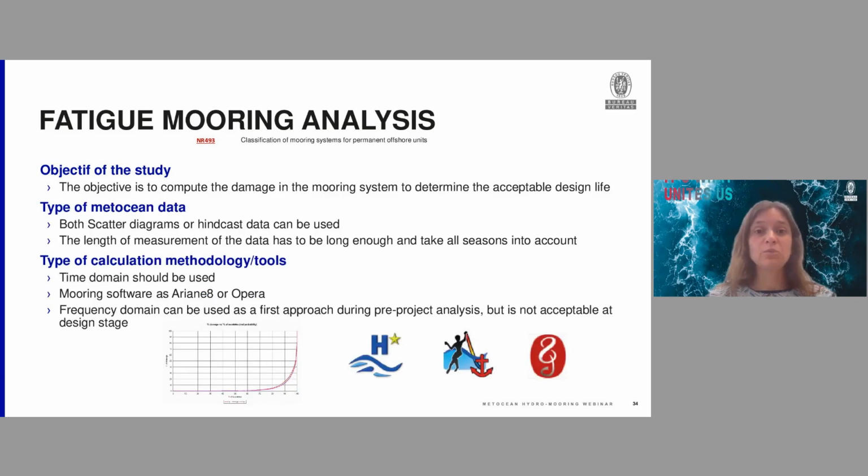And then fatigue mooring analysis. In this case, the objective of the study is to compute the damage in the mooring lines to determine the acceptable design life of the unit. For this kind of study, we can use both scatter diagram or in-case data. Still, we have to be cautious to use a length of data sufficient to have accurate results.